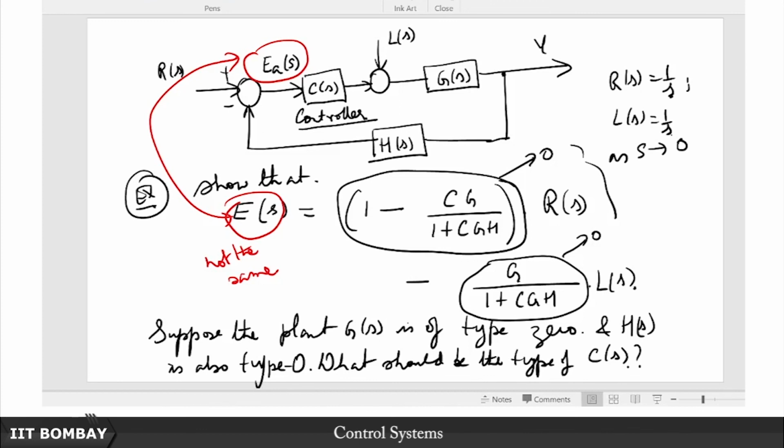Okay, but we will see that this Routh-Hurwitz array will do much more. Short of giving us the exact roots, which is of course a difficult computation to make for higher degree polynomials in general. In fact, beyond 4th degree polynomials, you will not have any foolproof method that will give you a closed form expression for the roots. You will only have to resort to numerical methods, right. So short of giving us the exact roots, Routh-Hurwitz does a lot.